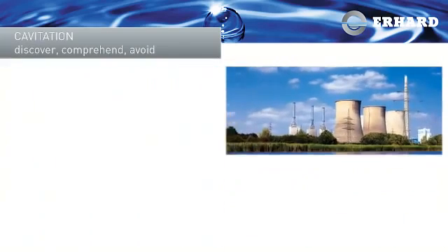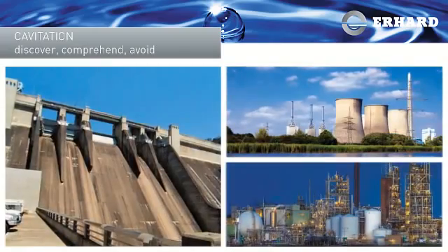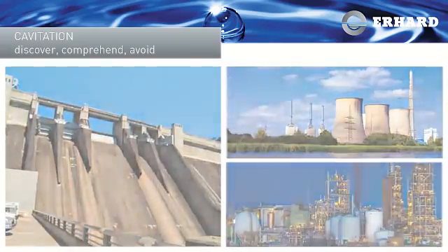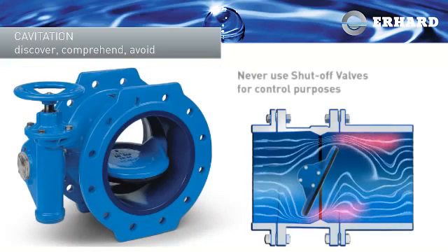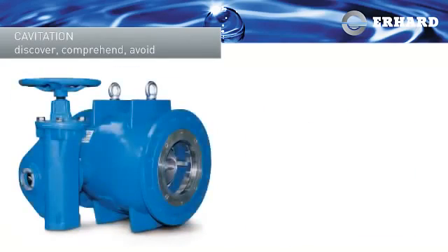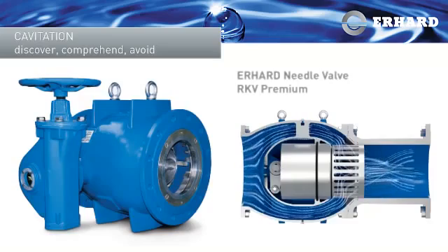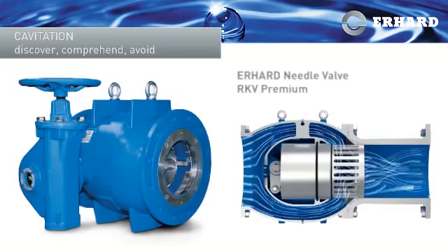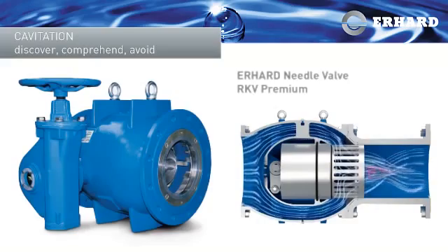Yet which is the correct valve for your special application? This is where expert advice is needed from ERHARD specialists. Above all, it is important that shut-off valves are not used for control purposes. ERHARD has a large number of high-quality control valves for this. Pure physics makes cavitation unavoidable even in these, but suitable measures reduce it or make it harmless.